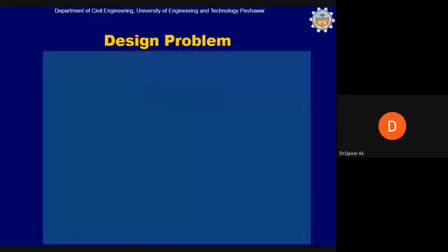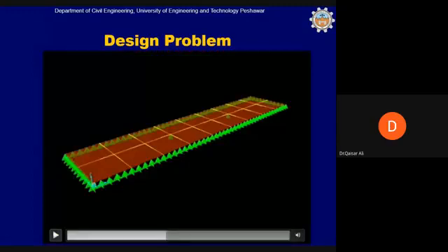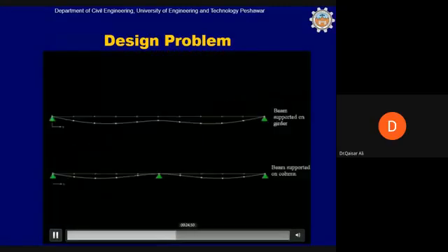You can see in the deflected shape. So for this reason, we have chosen a 36-inch deep girder. If we further decrease the depth of this girder, then this part, which is a curvature up, means that negative bending moment is developed here, and some kind of resistance is offered by the girder to the beam in order to minimize the deflection of the beam at this point. If this is not done, then this whole point will come down. Deflected shape will be like this.